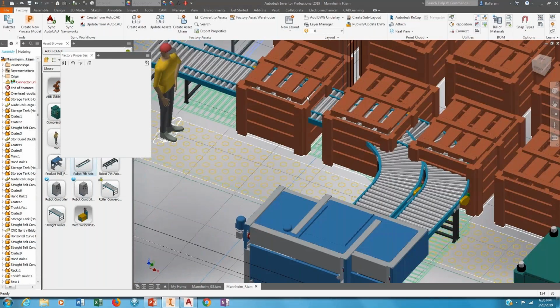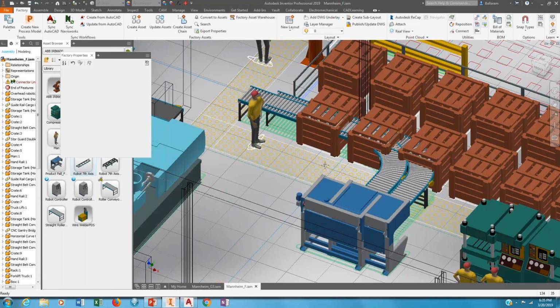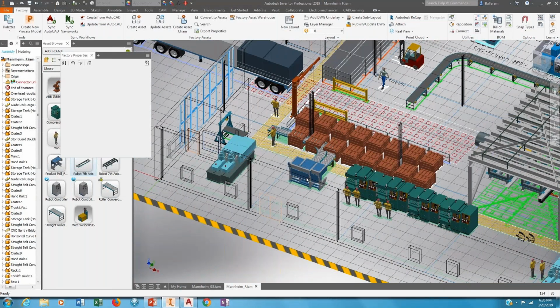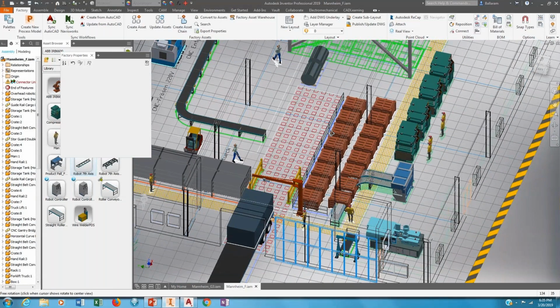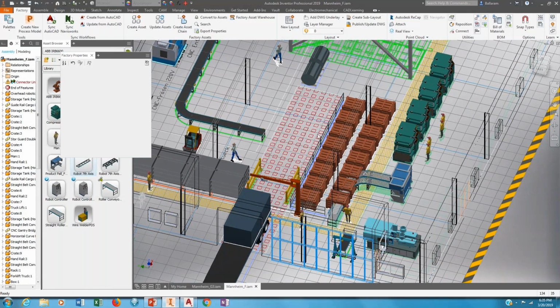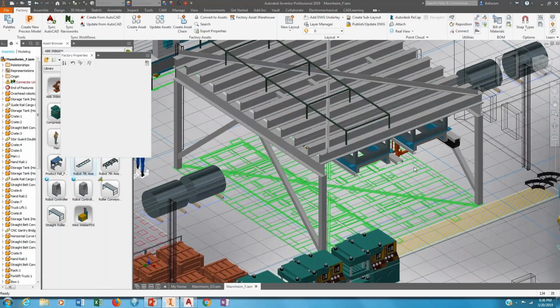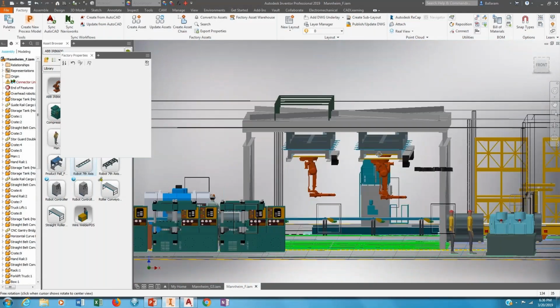You can see there's some of the components clashing, so it's going into each other. That would need to be modified, and that will happen in the 2D environment, or it could happen inside here. We just got to reposition it, but it's a lot easier and a lot better if we use a workflow where we modify it in the 2D environment.